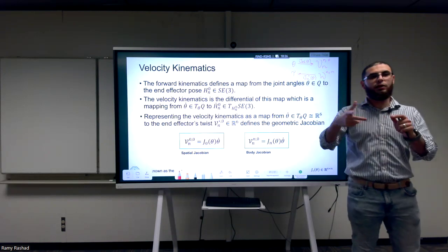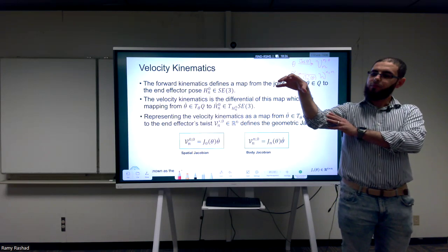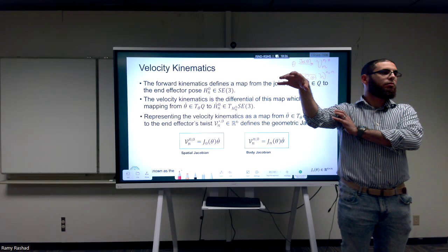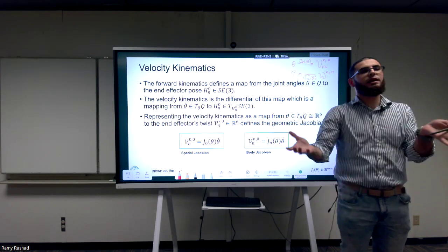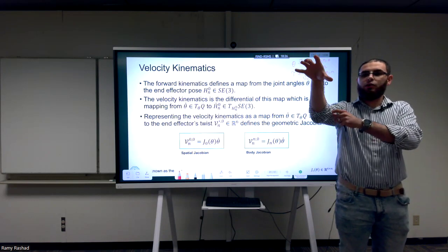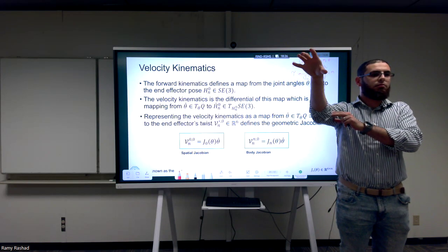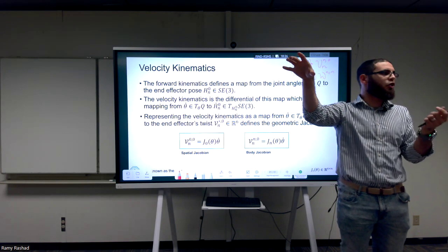So imagine that you have a robot arm, and what happens when you set all of the torques to zero? The gravity makes it fall down, right? So the first thing that people do, the basic thing, when you want a robot arm that just stays there when you turn it on, what is it? Cancel the gravity. Gravity compensation, right? What does gravity compensation mean?